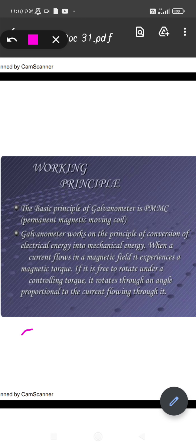Now what is the working principle of it? We know that whenever a current carrying rectangular loop, with copper wire wound on it, is kept in between the two magnets, these magnets produce a couple of forces, one force acting in the inward direction and the other acting in the outward direction. These two equal forces in opposite directions will make this rectangular loop rotate. This rotation allows the body to rotate, that is, the pointer rotates due to this itself.